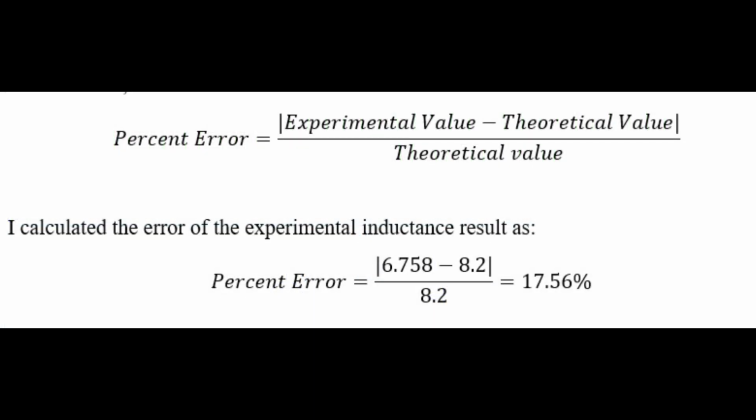The other causes of error might also be the resistance of the wires, the small inductance of the resistor, the heat increase changing inductance and resistance, and the noise from the outside which interfered with the AC signal. Overall, it can be said that the inductance can be calculated by only measuring the voltage across the inductor with acceptable error. However, the equipment must be tested thoroughly to ensure that there are no malfunctions.